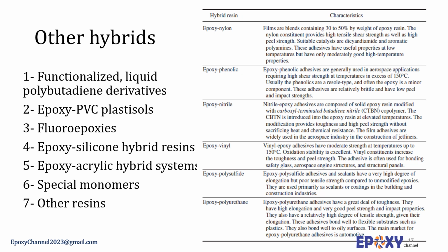Fluoroepoxy resins have also been developed that, when cured with silicone amines or fluoroanhydrides, show substantial hydrophobicity. As the resin's fluorocarbon content is increased, its hydrophobicity also increases. Adhesives made with these compounds showed much less degradation in glass transition temperature as a function of exposure to high moisture environments. Epoxy-silicone hybrid resins have generally been developed for use in the molding of microelectronics packages.